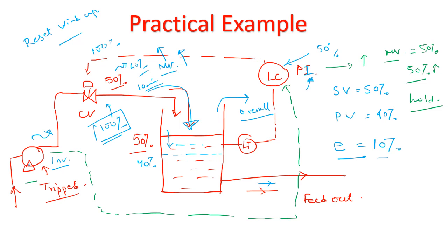So this is anti-reset or anti-windup basically, and there are many ways to implement this. Digital controllers now come with this feature inbuilt. It was a major problem when there were analog controllers earlier, but now the digital controller comes with lots of features, and anti-reset or anti-windup is one of the common features present on all digital controllers. Still we need to configure it well, and we need to see that we have not bypassed this particular feature.